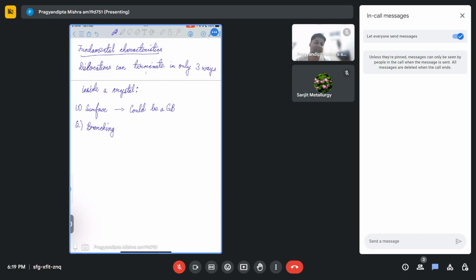Any reaction, any deformation, etc. Anything happens because the material is trying to reduce the energy within its structure. Now, with respect to dislocations also, the material will sometimes try to reduce its energy. And one way to manifest that is to form branches. So instead of having a very long dislocation like this, sometimes the dislocation will branch out into 2 or 3 dislocations.